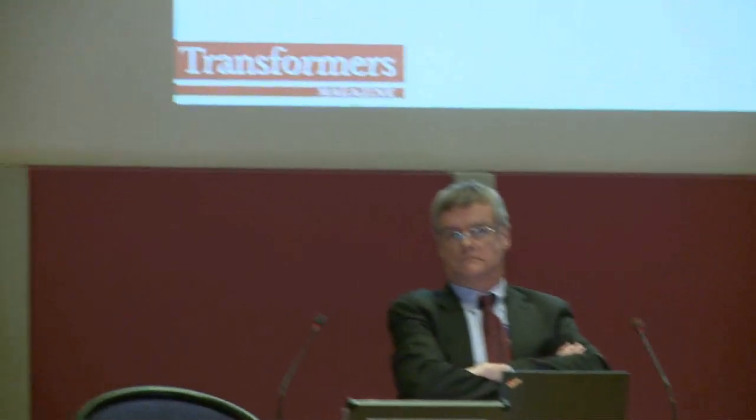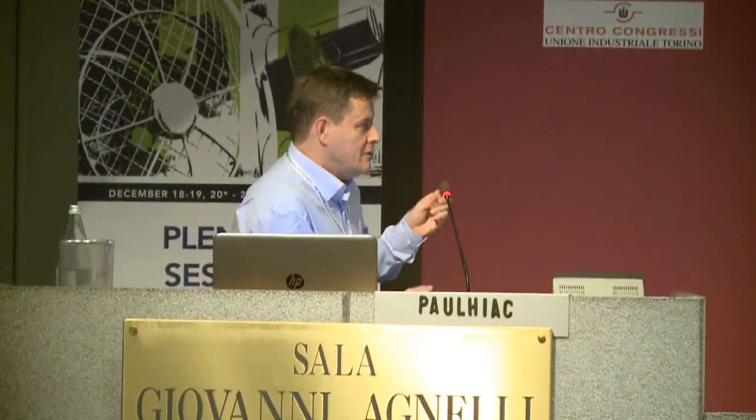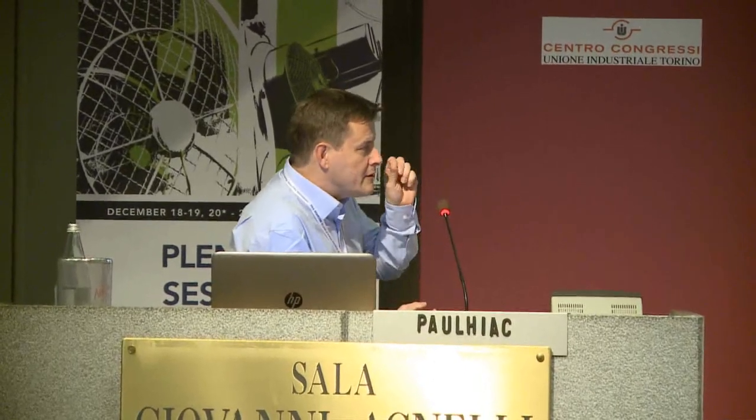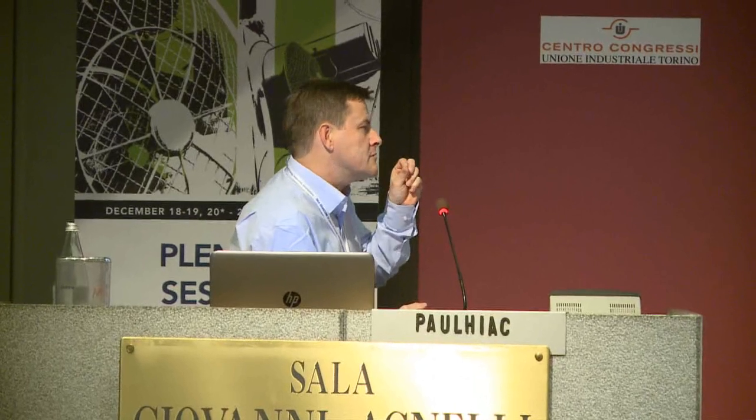If I can just add something. Yeah, for sure, when you have a fault in a transformer, you're not talking about 2 or 3 ppm. You clearly have all the gases that go up. And then, I don't think it's an issue. The sensitivity or the exact value is no longer an issue.